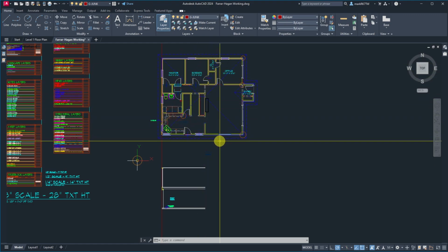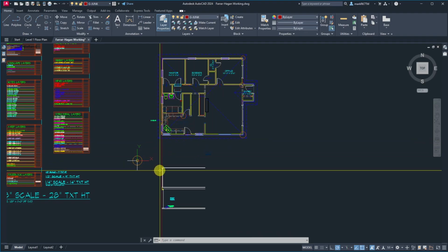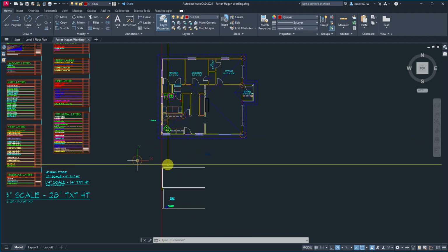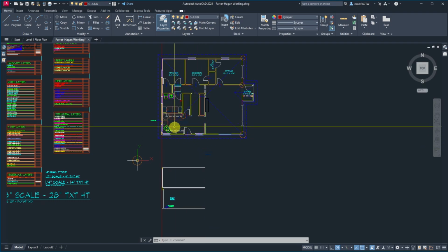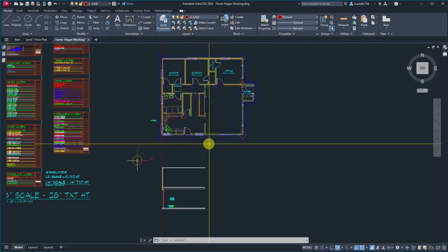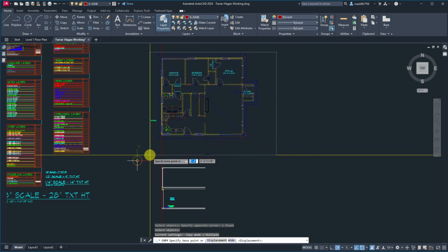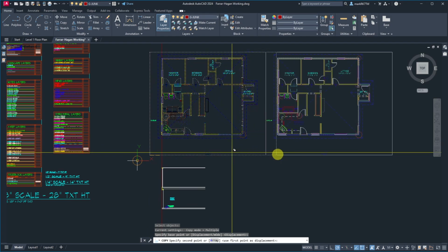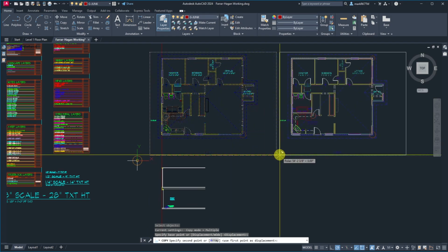And the shallow ones I think are going to be where I'm going to start my bird's mouth as you typically would, and then I'll adjust the bird's mouth on this one. And I want to see what happens, see if it goes the right direction. So first thing we're going to do is copy this. And let's just get a feel for how much distance we've got. So that's 54 feet. So if I copy that with room for notes, let's just make it 100 feet.